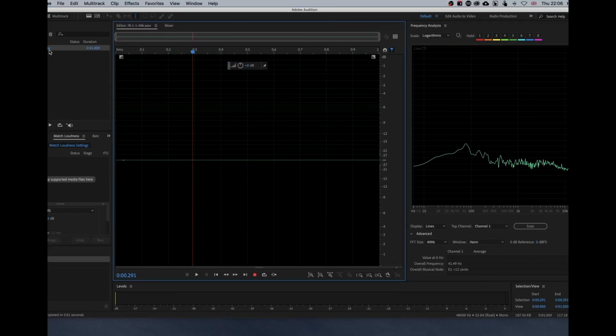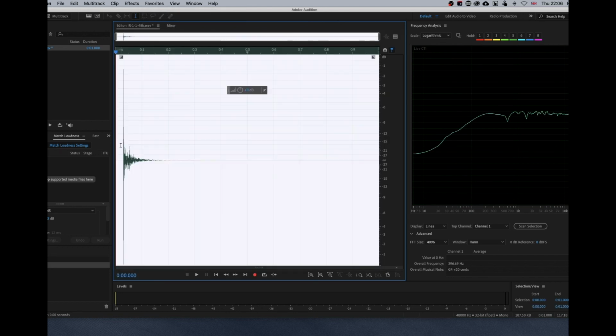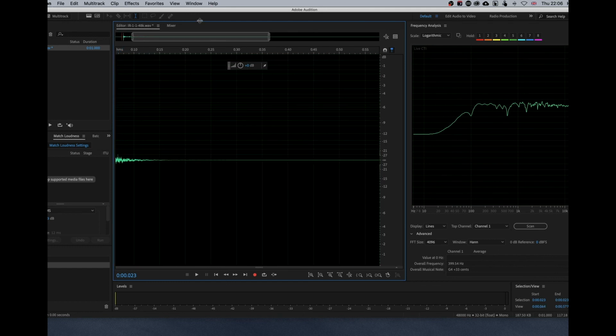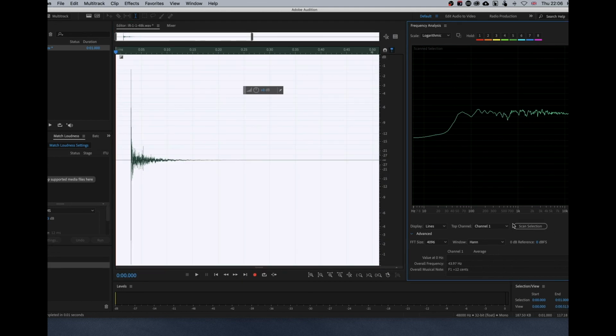This is actually a response I already captured previously in my home office. As you can see here, this is a tiny signal. It's because my microphone preamp gain was not high enough, and also we're using 32-bit audio, so the SNR, signal to noise ratio, is still pretty large. We can see this impulse when we normalize the signal, followed by the reflections. And you can quickly see the frequency response.